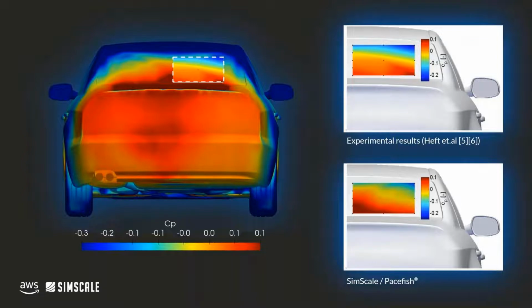The solver predicts slightly higher pressures in the very middle of the windshield, compared to the measured data, but this eases away to be closer to the experiment, away from the center line. The amount of probes measured here is also significantly lower than on the front of the fastback, so the inaccuracy of interpolating experimental results also plays a significant role in comparison.